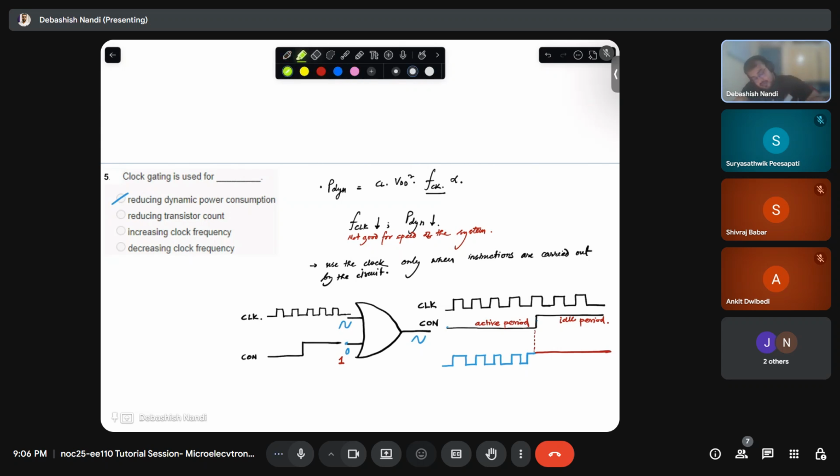Now if I consider this overall system, this frequency, I would rather use the term effective frequency, will be lower. This we call a gated clock. Why am I saying so? For sequential circuits, let's say your device is positive edge triggered, okay? After this point, you will not see any positive edges, right?